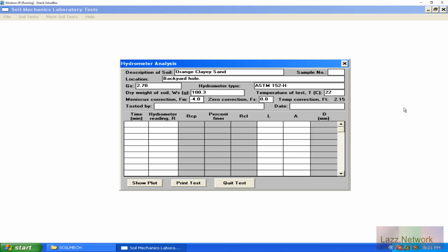Regardless of temperature, it should relatively stay at 0, unless it's cold to freezing or simmering to boiling hot water, then your hydrometer is probably going to move around. Typically when you do this test, your hydrometer should be zeroed. Over time with use it may not be, or it might just be a manufacturing error. Maybe they didn't curve the glass just right when they put everything together. And you might notice when you put it in, it might be in between 0 to 1.